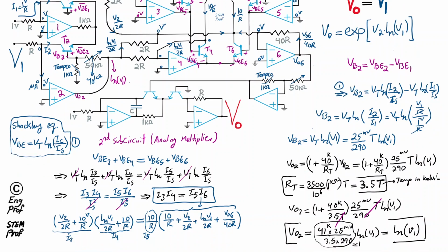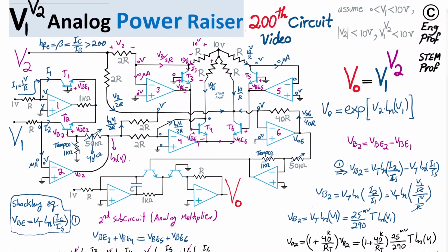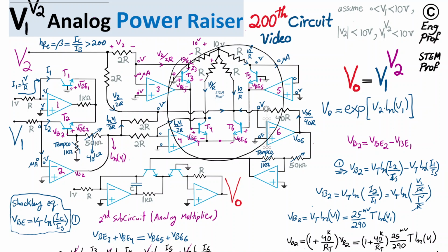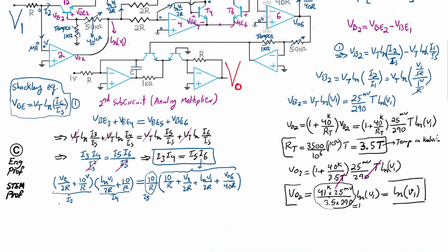If we take care of just simplifying the whole thing across this equation that I just wrote, and again making the assumption that, as I said, these four transistors are matched transistors, and the resistors that are selected, the R resistor, they are with good tolerance, like thin film or something less than 1%, then when we simplify this whole thing, when we simplify this interesting equation, the outcome will become effectively just V out 6 equal to V2 times ln V1.